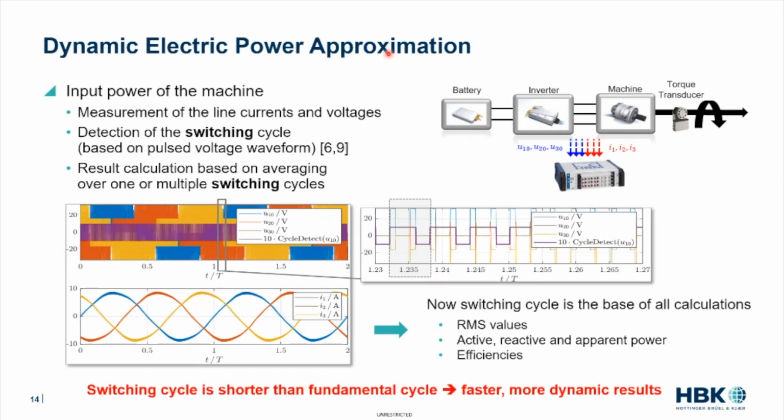And this approximation, the accuracy you can achieve with that, is a function of the relation between fundamental frequency and switching frequency. There is a lot of math involved here, but I will show later in a real world example that it is pretty accurate, but it is not 100% accurate. And as said, it's a function of the relation between fundamental frequency and switching frequency. So let's see how that looks.